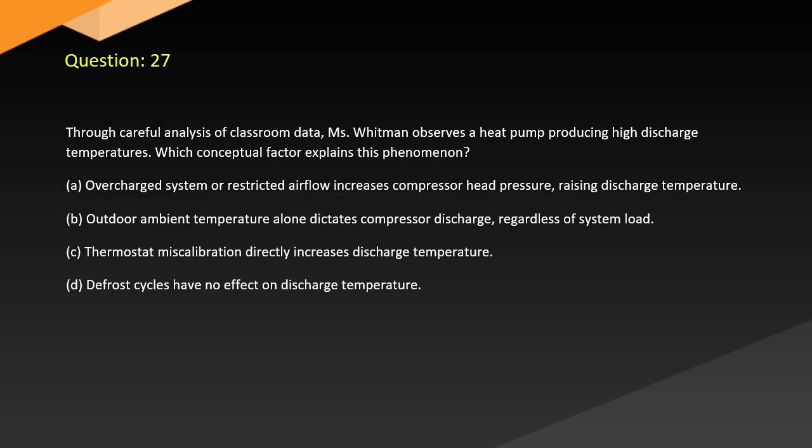Question 27. Through careful analysis of classroom data, Whitman observes a heat pump producing high discharge temperatures. Which conceptual factor explains this phenomenon? A. Overcharged system or restricted airflow increases compressor head pressure, raising discharge temperature. B. Outdoor ambient temperature alone dictates compressor discharge, regardless of system load. C. Thermostat miscalibration directly increases discharge temperature. D. Defrost cycles have no effect on discharge temperature.